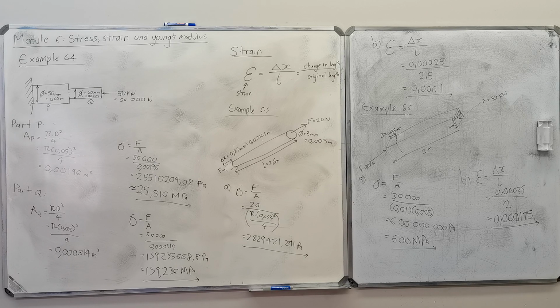Now let's move on to unit 6.2 on page 146. Shear stress. Not stress, shear stress. A shear force is a force that is applied sideways onto a material. It's not applied vertically. Remember with the other one, we were pulling it like this or like this. This is applied sideways. A situation where a shear force would occur is wooden block A attached to wooden block B by means of a nail.